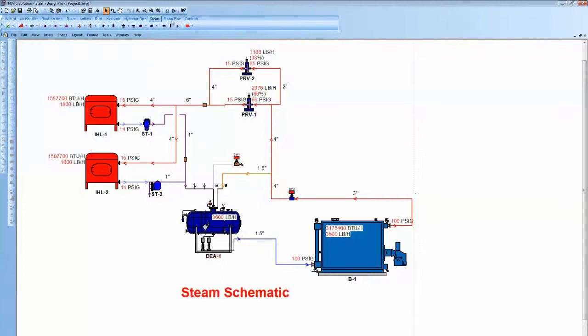Now you can always come into the steam pipe and start putting strainers on here. Just drop them right in there. Really showing what you want on there. Here's a little relief valve that would go on that, right? You want some unions on there. These are minor components. Just that check valve, move on check valve in there. Just come over here, maybe you want a gauge on there. That's how easy it is to do.